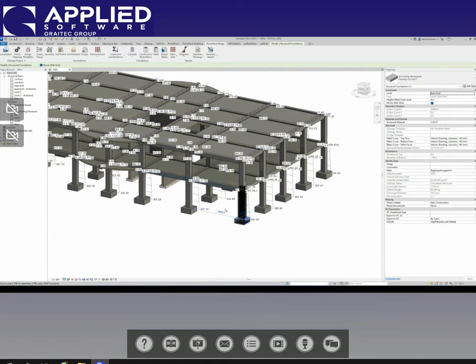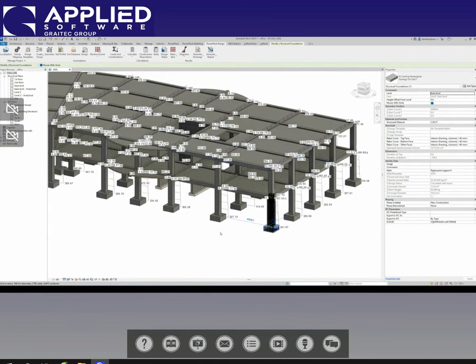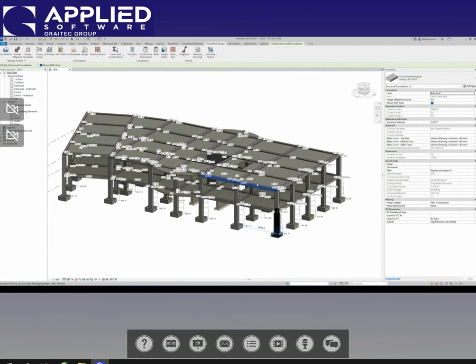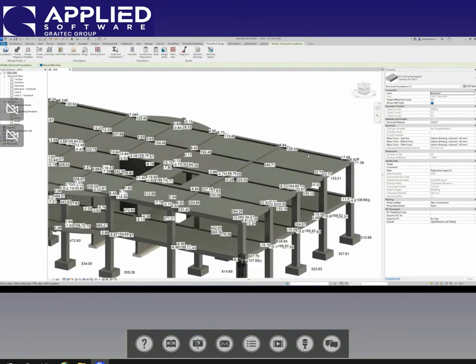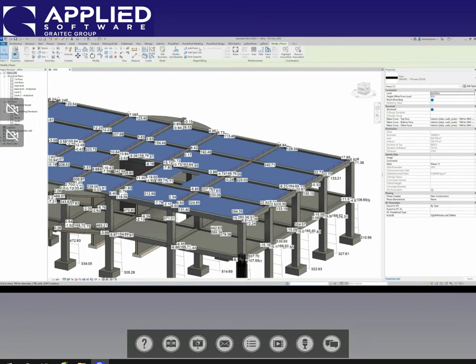The other very interesting tool that we have here in our Power Pack is rebar placement for your slabs. If you remember, we also brought in our rebar area from Advanced Design, which we can use in that calculation to apply our rebars to our slabs. So in this case, I can use our Power Packs again. You just select the slab, go to Power Pack Detailing, and here I have the slab tool. I will click on Edit Window. So now we are opening our slab directly in a separate window, which is mostly based on our rebar areas.